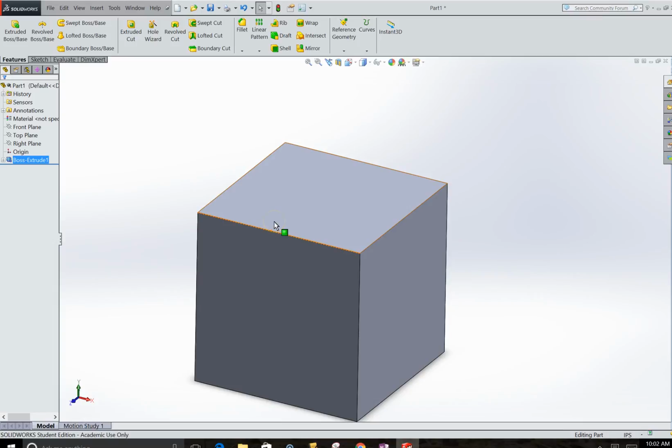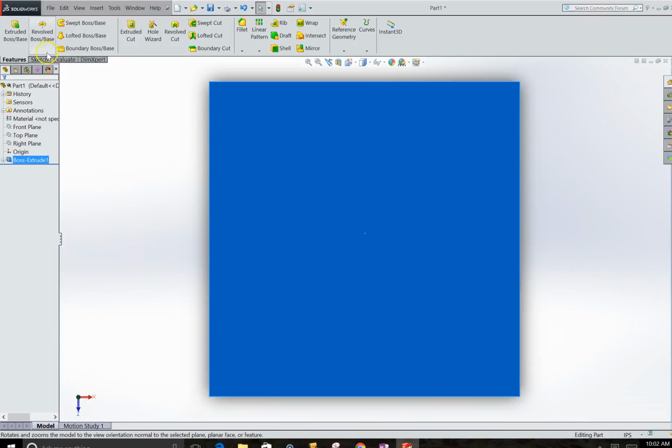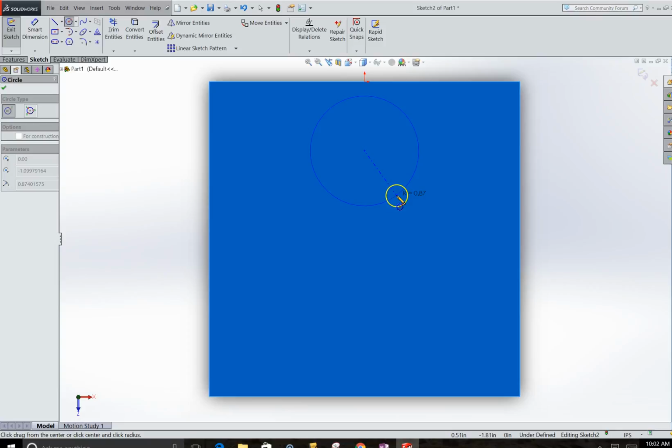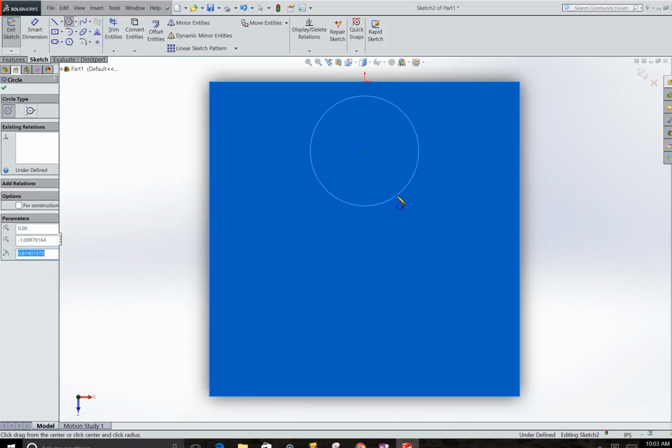Okay, let's just pick a couple of surfaces to draw some type of sketch on that we can cut between. So let's start with our top sketch. I'll go normal to it. I'm going to sketch, and let's just do a circle. I'm going to put this circle somewhere about right here, so it looks like I'm vertical from my origin.